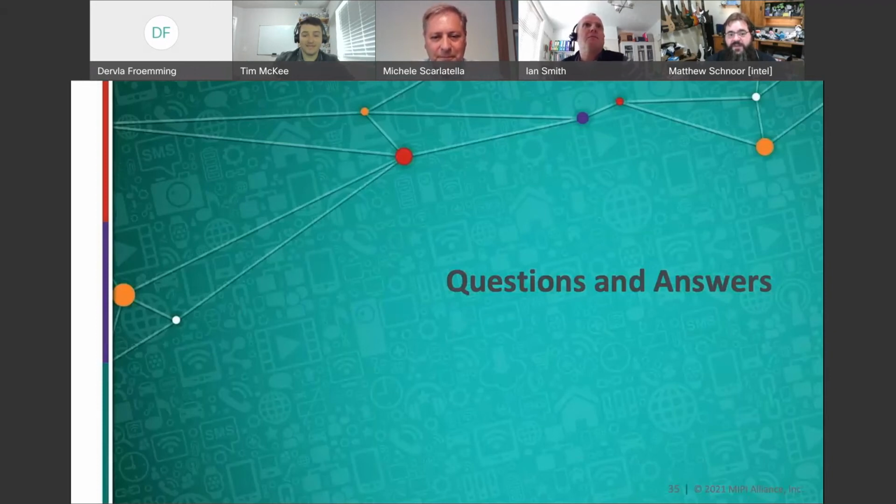I think an I3C device could simply just NACK the transaction. Just provide a NACK on their dynamic address, and that's the indication that they're not ready yet. If it's a write followed by a read, and they need time to process that write and have a response ready for a read, the target device could just NACK the read and have that be the indication that they're not ready yet, and then try the read again, and then after a couple attempts, there's a timeout.